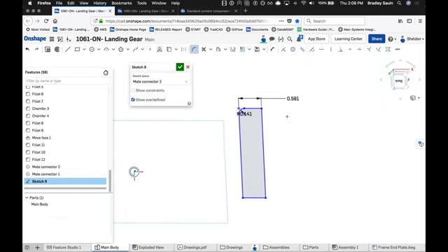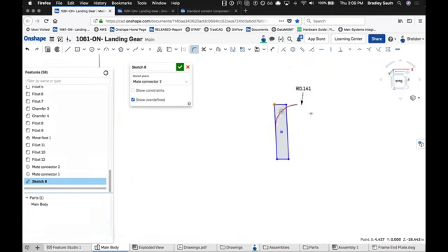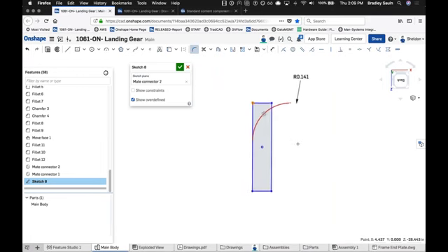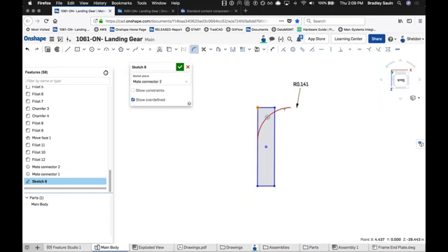Got that value. There we go. Let's try this guy. Now with Onshape, we do show a quick preview of where the current sketch fillet radius lies. So instead of just completely failing out or not giving me any feedback, I do see the existing sketch fillet radius as it's being applied, and then can choose to drag it to a correct positioning where I now see blue lines telling me that's actually going to work and will be accepted.